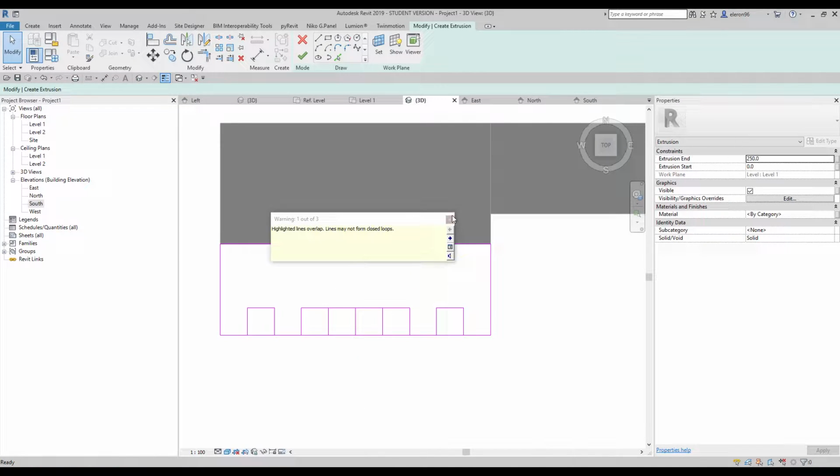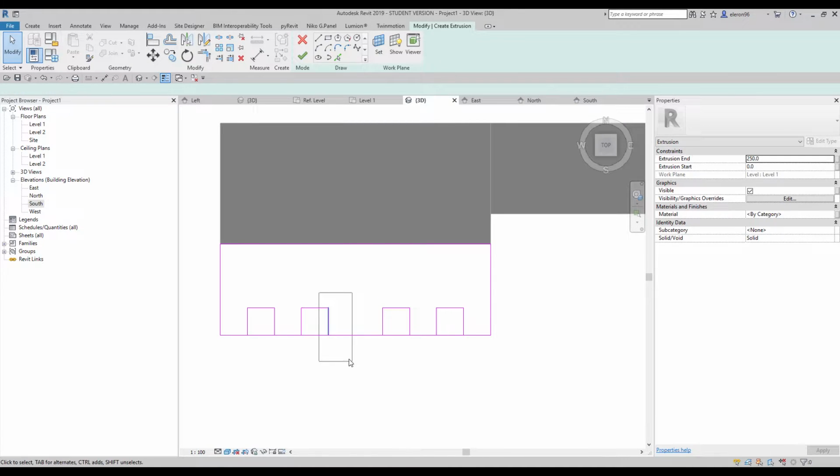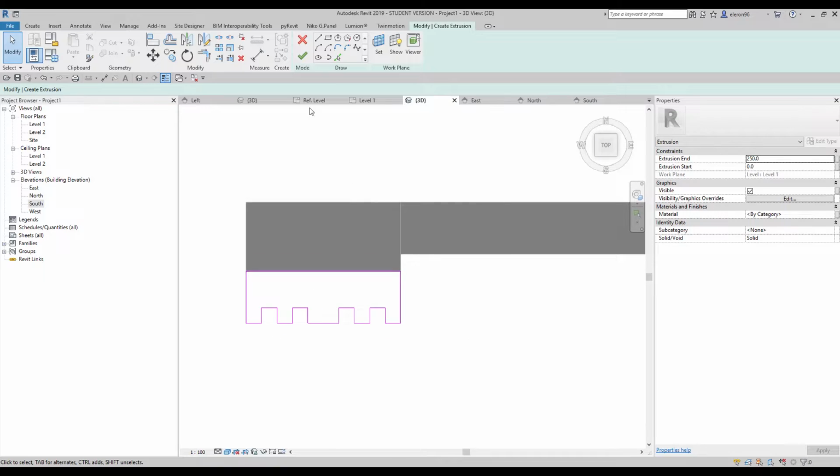Okay, yeah, of course I know we have the intersection. So let's delete this line, that line and that line. Here, how many lines do we have? We have two lines. On this side, only one. On this side, only one. Okay. And let's use the split now. Now we need to split all these parts. And after that, I will use TR, or you can find it as trim, to connect all these parts. So I choose only the part which I want to save. So I want to save this part, and I want to save this part, not that one, only this one. And this is the logic, how it's working.